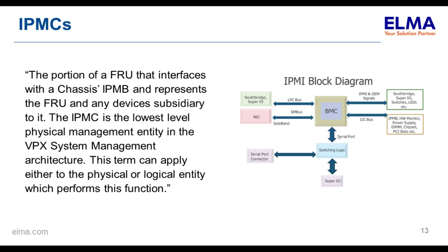The IPMC is the lowest level of physical management within the VPX system management architecture. This term can be applied to either a physical or logical entity, but the IPMC could actually be on an FPGA, or it could be on a separate microcontroller.